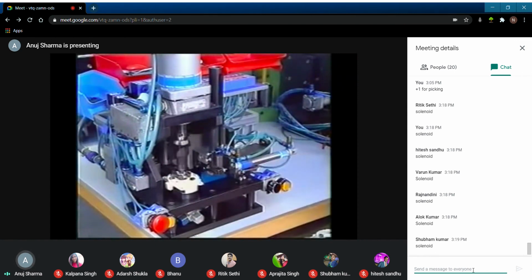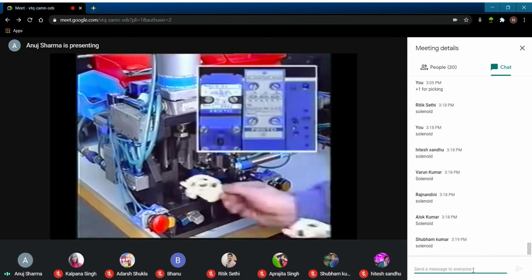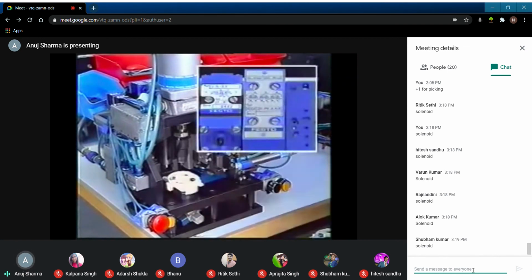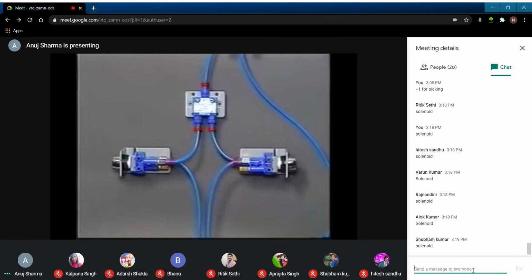Often, machine circuits use multiple AND valves. To simplify circuit plumbing, you can use a valve block containing multiple valves. For example, this block contains 3 AND valves. Another type of logic valve is the OR valve. When one or more signals is received by this valve, it produces an output.